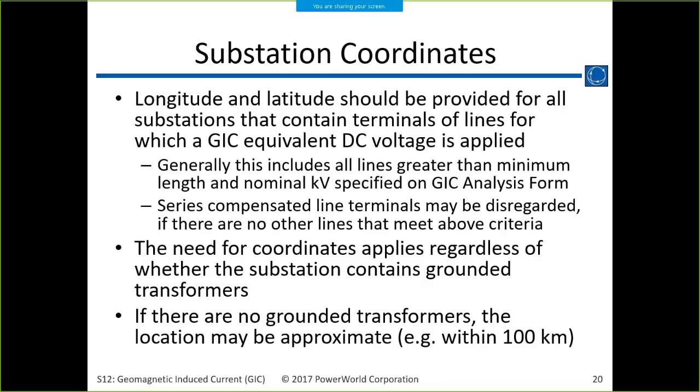If you've got big GIC at Grand Coulee, that might be a big deal for the transformers that are affected thermally. But from a system standpoint, it might not be so bad because you've also got a lot of VAR resources spinning right there to help prop the voltage up.